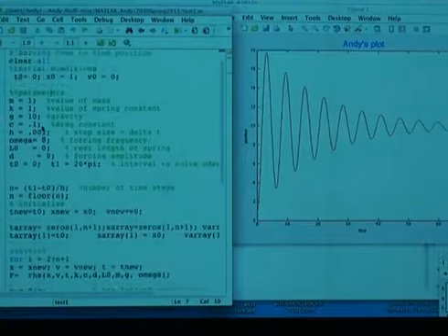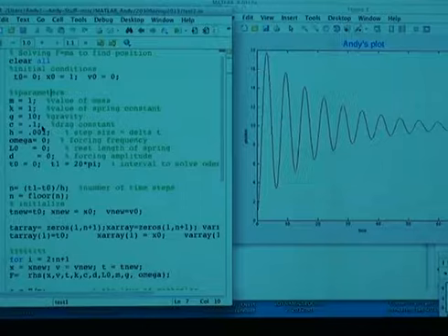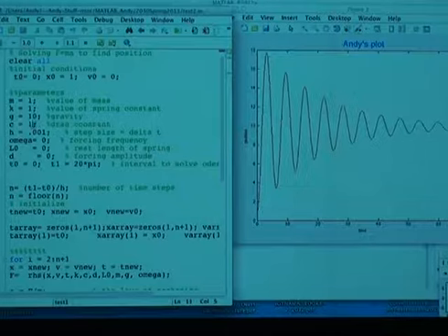Yeah, the homogeneous in particular has to do with the right-hand side. The damping is still on the left-hand side because it was a constant times x dot. Okay, so that was with the m x double dot plus c x dot plus k x equals 0. So this is the damped homogeneous solution. I can put in bigger damping here, like a 1, and then it will be very damped.